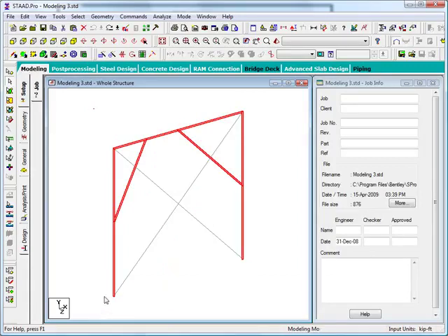It follows the same rule as the drag box in that if the midpoint of the member is included in the region, it's selected. If the midpoint is not within the region, it's not selected. So you can see that I just drew a selection region that specifically carved its way around the midpoints, or the crossing points, of the two major diagonals. And you can see that once I executed that selection, I selected everything except for those two diagonals, just as we expected.